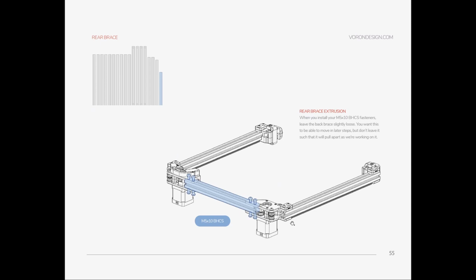Yeah, for this bolt, there are another two bolts on the bottom. For the second bolt, you need to install a T-nut as you are expecting. However, if you use the last hole of your rail, this T-nut is intersecting with the rail's T-nut. So that's why you need to leave the last hole of the rail empty. With that, the T-nut will have space for the placement and you can screw it.